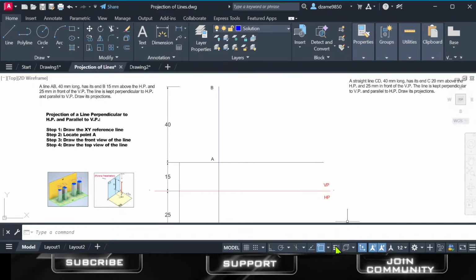I'm toggling the line weight display, LW display. When I click on it to activate it, it shows the density of the lines in the line weight. Otherwise they remain by default construction lines, not visible directly with the colors I just put there. I hope you've understood.